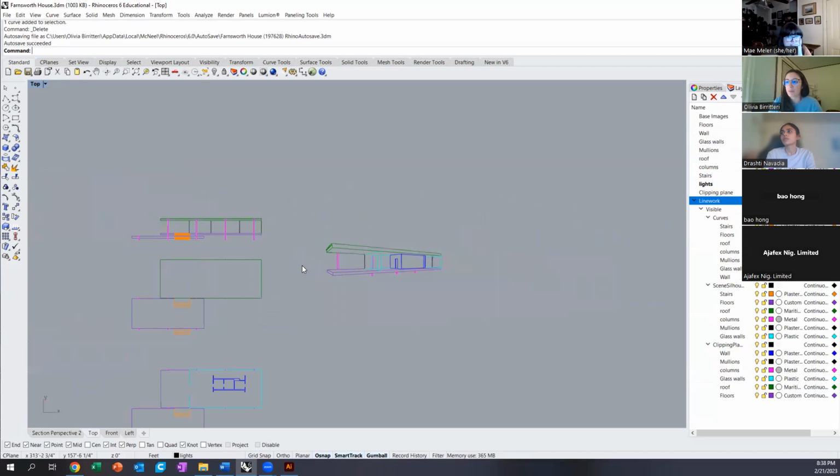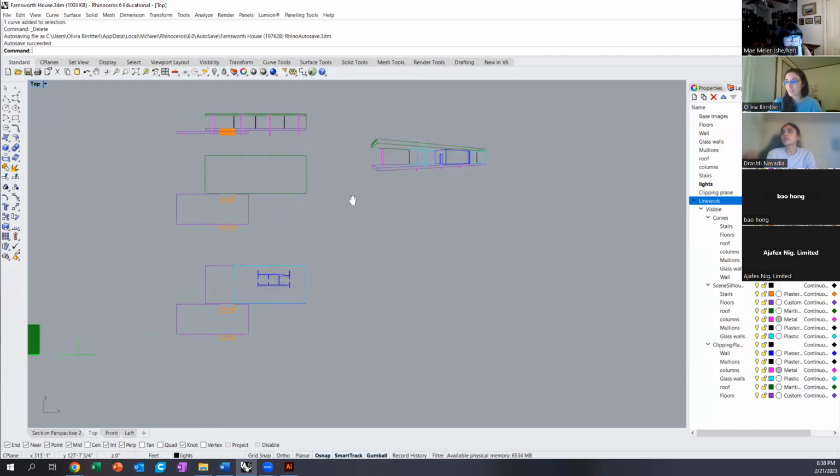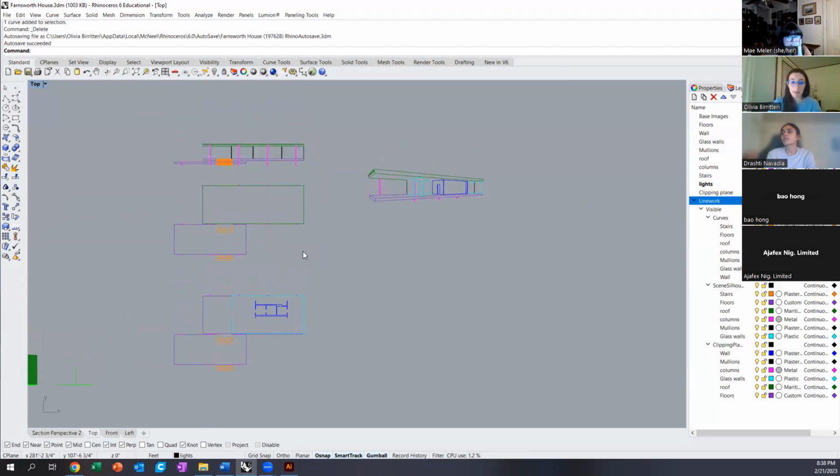If you have a complex shape, for example a cylinder, sometimes cylindrical or spherical shapes don't export very well with Make2D, so sometimes you have to fix the line and connect it all back. But generally, as you see here, this is a really quick way to make all of your drawings without having to draw them from scratch.